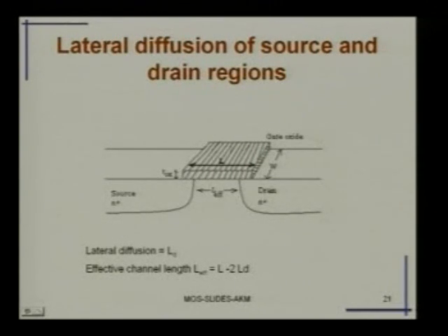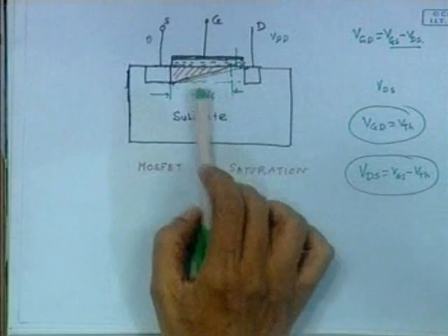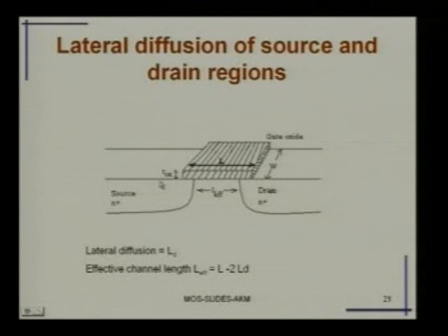Only thing I will just mention is that the gate region creates a capacitance, that is CMOS, we have seen, and this capacitance normally we were assuming to be flat. See, in this example we were thinking this is a straight line, but that does not really happen in the physical world. The reason being that when you diffuse the n-type material, say here, this diffusion will not be terminated straight away. Some of the donor ions will permeate, will move towards below the channel region also.